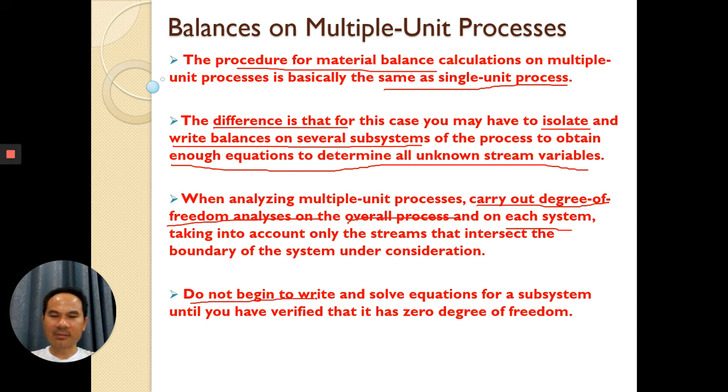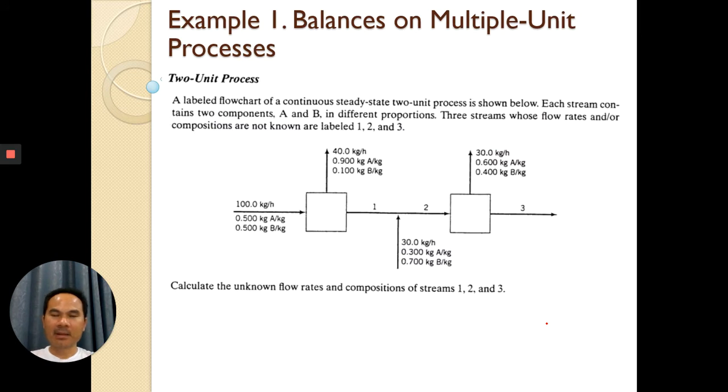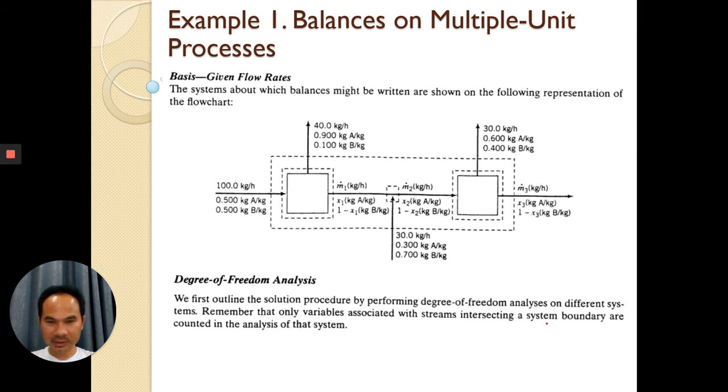You cannot write and solve equations for a subsystem until you have verified it has zero degrees of freedom. In conclusion, you have to verify that the subsystem or the overall balance has zero degrees of freedom. You have to verify this first. For example, okay.